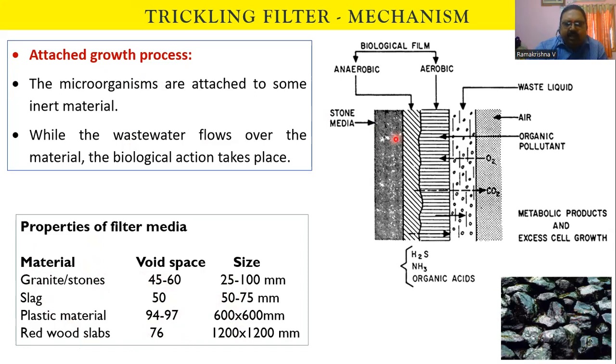Now the mechanism is depicted here. This is the material and another material is here. In between, the water is flowing from the top, and the upper surface is open to the atmosphere, so the air will come in contact with the water. The surface close to the filter media, we can't say stone media, it's a filter media, the air will be coming in contact with the liquid, and the surface close to the liquid and air will be under aerobic decomposition.